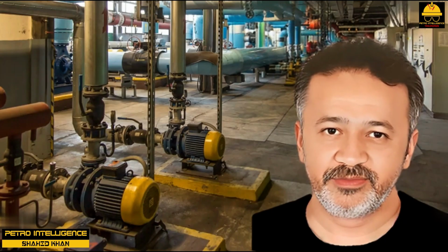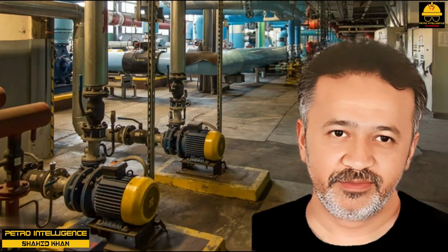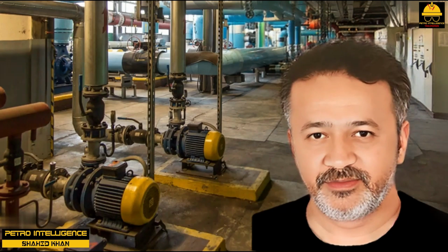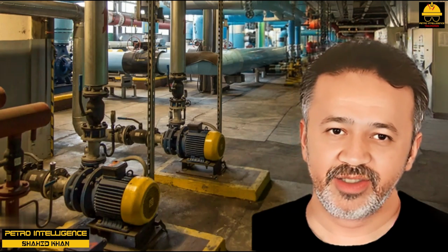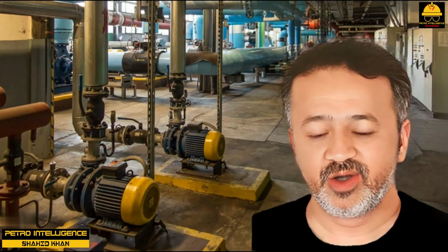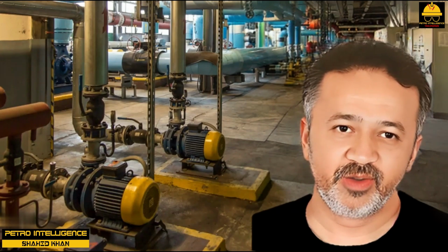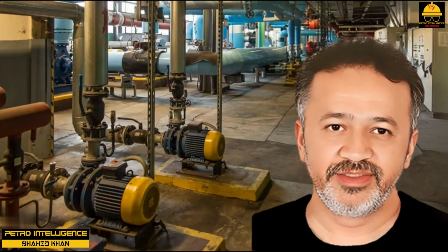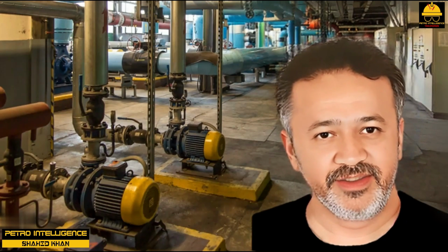Motor bearings. If you think a motor is running rough because of bad bearings, have it uncoupled from the pump. Run the motor alone and see if the vibrations persist. Motor bearings commonly fail because of a lack of lubrication. Most motors are lubricated with a heavy grease injected through a grease fitting delivered via a grease gun. Over-greasing can burn up the motor bearings. You need to follow the manufacturer's recommendations.